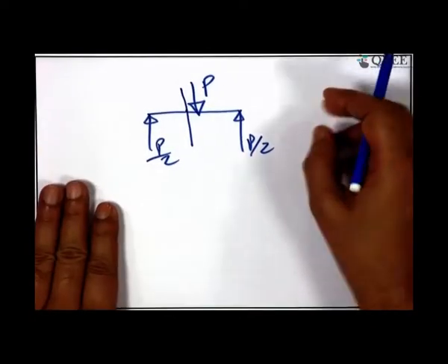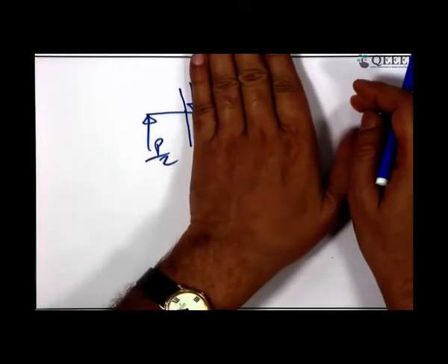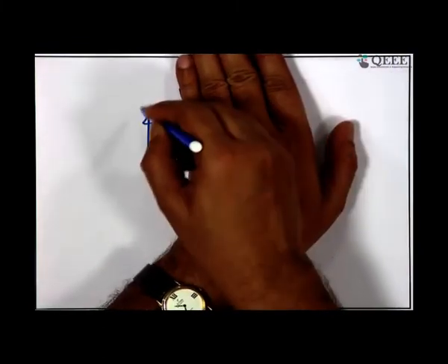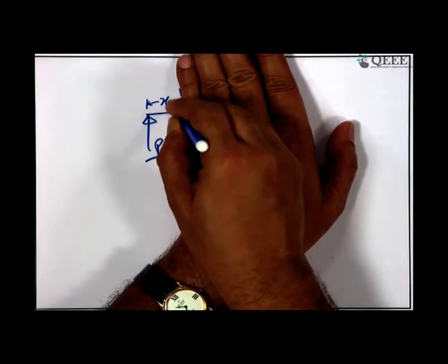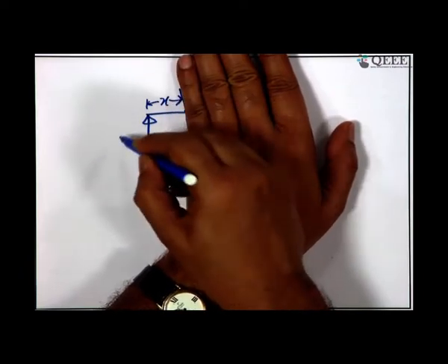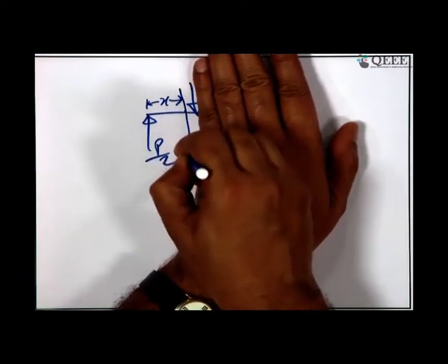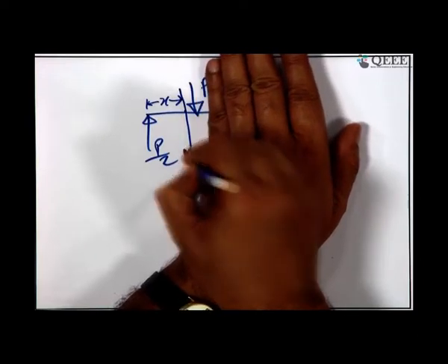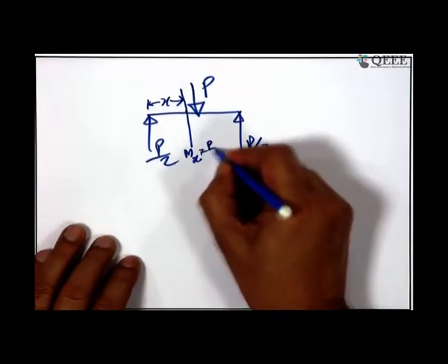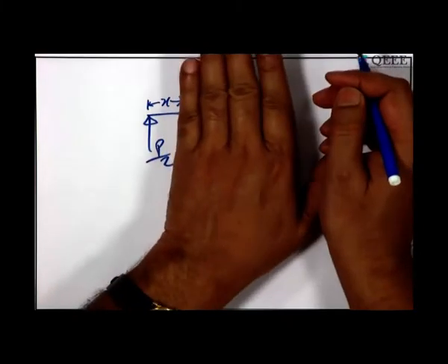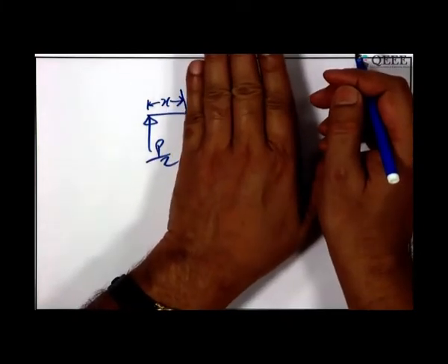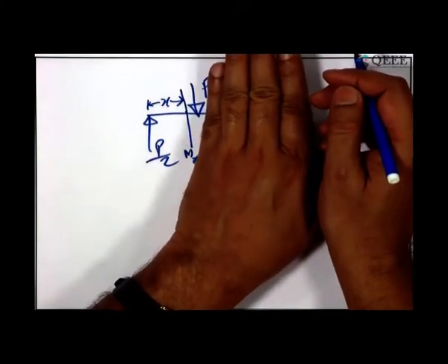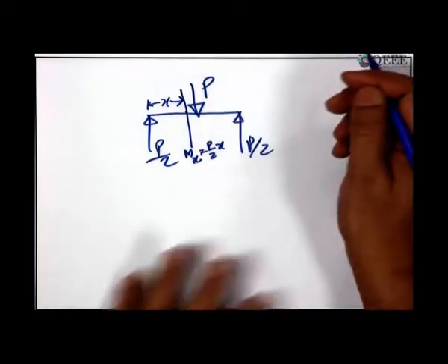So, starting from the left end, I must suppress the right end, and I will count what distance this load is actually acting, and then say that the moment at this section Mx is equal to P by 2 into that distance. Like that I will go ahead unless I have a change, and then I can incorporate the other force which is coming. Like that you draw the bending moment diagram for a structure.